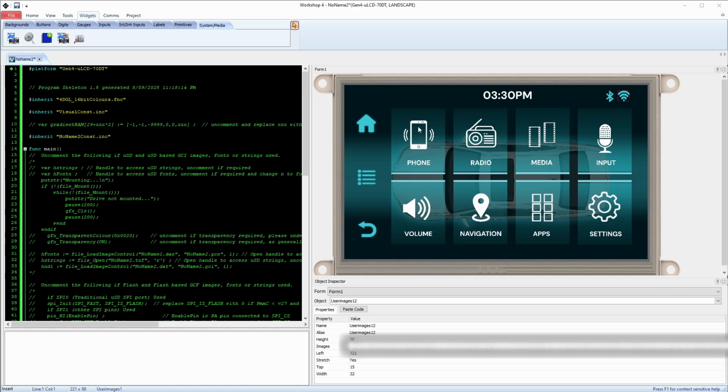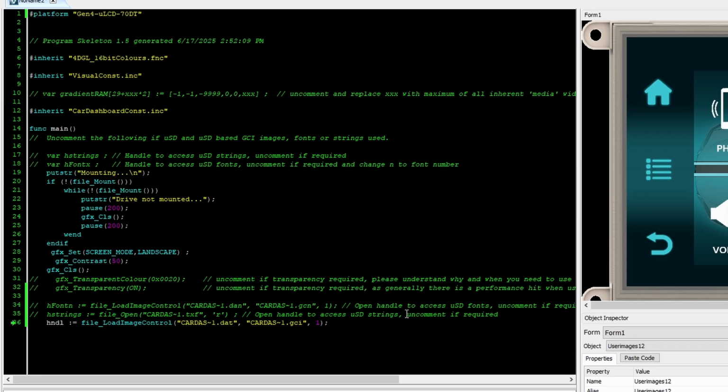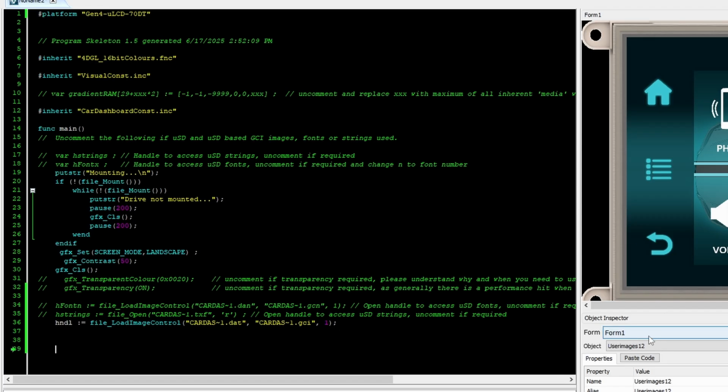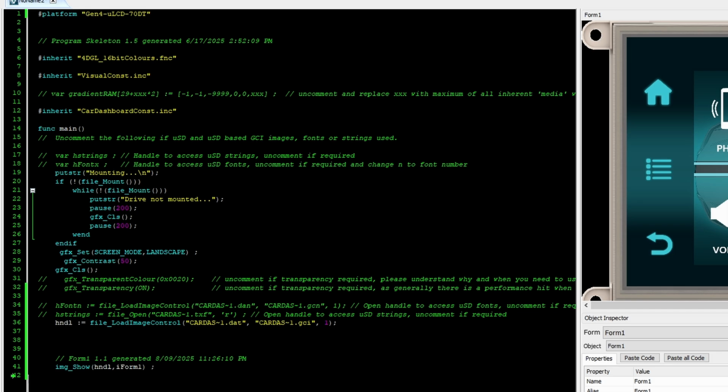Moving on to the code of this program, it is relatively simple. I'll give you a brief rundown of what is going on while I type it all out. The overview of this 4D GL is that in this code, we are doing all of our basic setup, such as loading graphics, booting and mounting the SD card, and then we are triggering a loop that is toggling our user images between frames 1 and 0 every 500 milliseconds. This is to create some simple 2-frame blinking animations.